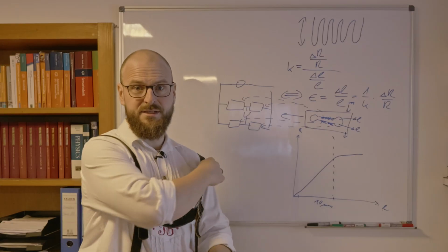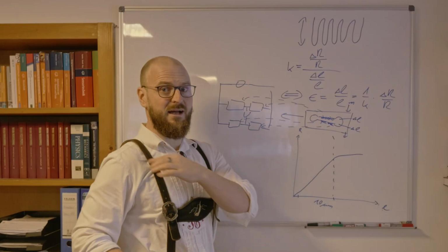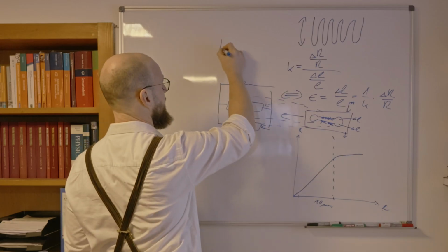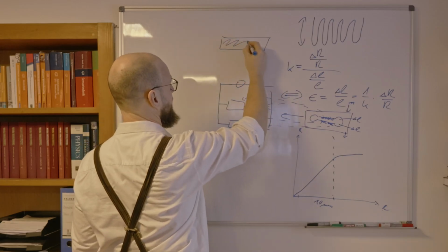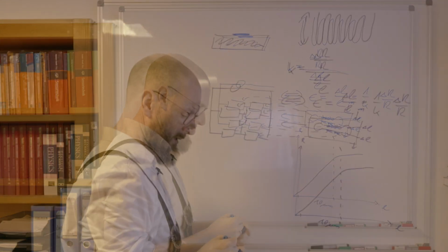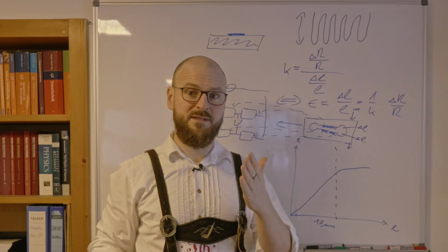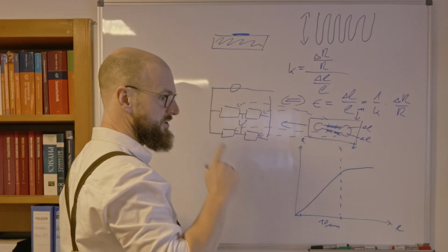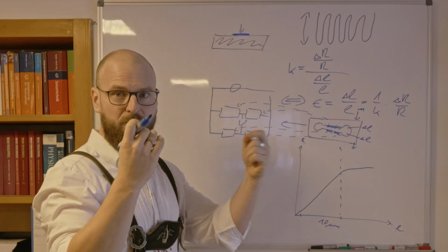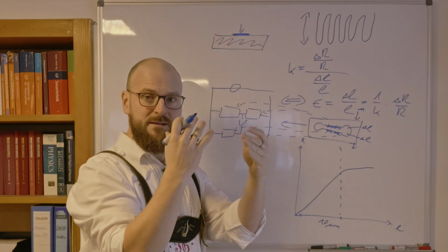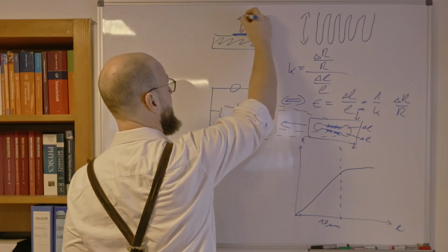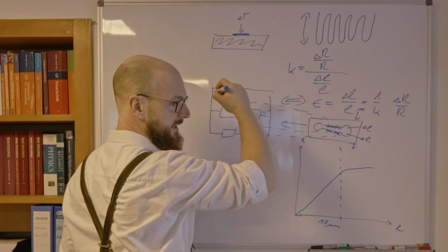Moreover, strain gauges deliver us a second possibility to cope with temperature change. So imagine we have some measurement object over here and place some strain gauge on it. Temperature will induce several changes. The first change is due to the electrical resistance. We will get some temperature change due to electrical effects.